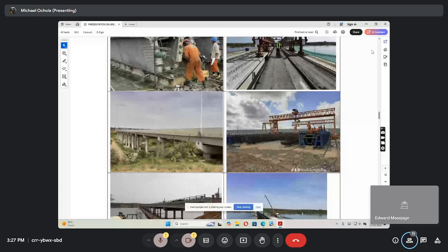So you can see now they're building using this crane. They fabricate this in a yard. This area, that's where they fabricate the girder. Then they will use a low bay truck to transport it to a good place where they will bring it here, then they begin somewhere up here, level, then the overhead gantry, like what you're seeing down here, begins to lift. If you go to YouTube, you are going to get very good videos on how these girders work, and you'll be appreciative. So these are the works on the deck slab reinforcement.